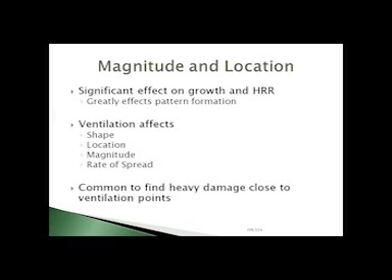And the rate of spread, obviously, as you increase the heat release rate, you increase the products of combustion, you put more heat into the room and places for it to spread, and you're going to spread that fire faster. It's very common to find heavy damage close to ventilation points just because you've increased the heat release rate and the plume temperature so much right there.